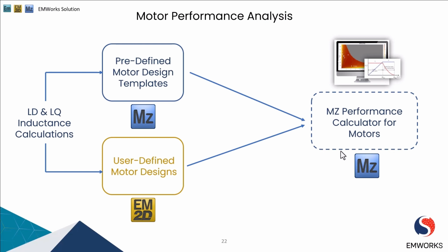So far we have obtained the performance analysis of a high torque, low speed permanent magnet generator using the EMWorks 2D software, where we observe its on-load and no-load analysis, such as back EMF, cogging torque, electromagnetic load torque, and the losses, whether it's hysteresis loss, eddy current loss, or the excess loss. We also use the EMS software to get its thermal and structural analysis.